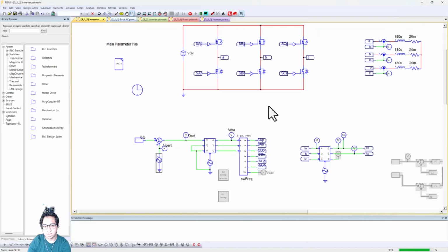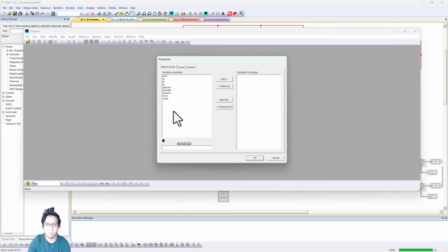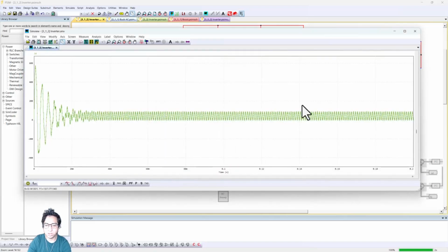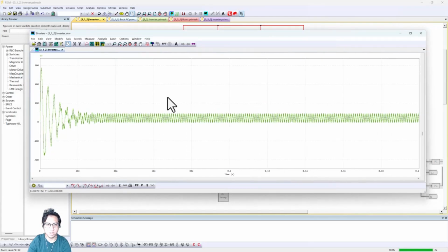The best step to debugging an AC sweep is to look at the transient simulation. PSIM doesn't use average models. It uses the converter transient simulations to build an AC response.